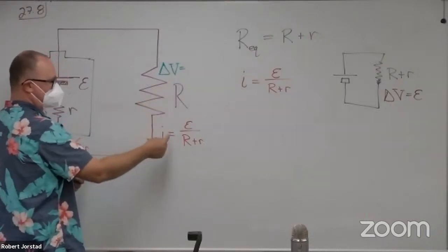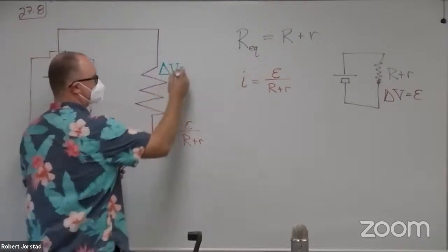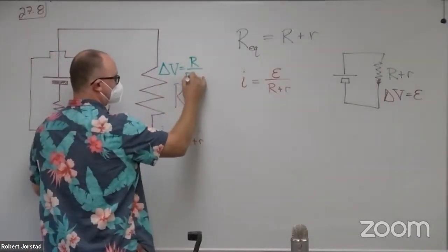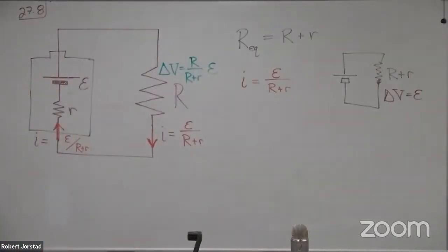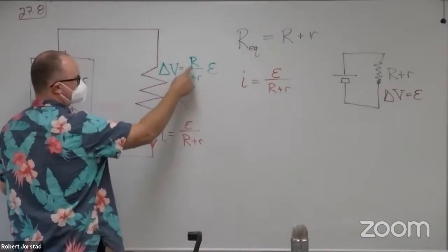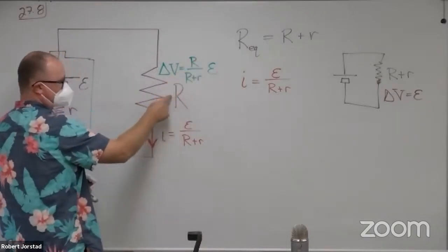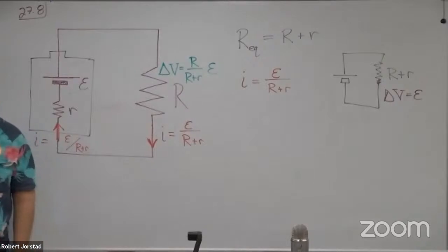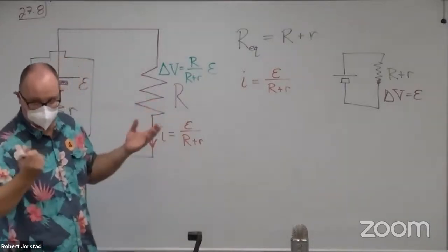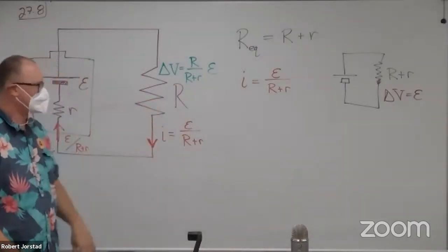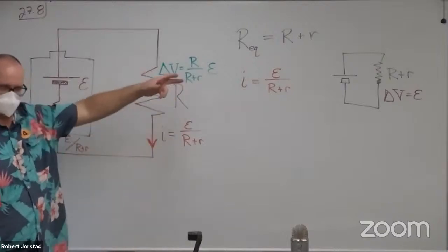So the voltage is this current times this resistance. It's close to E, but it's not quite E. It's actually the ratio of this resistor to the entire resistance. Remember I told you that before? It was the voltage divider equation I alluded to. I'm like, oh, if you saw this cool trick, you could have known this answer. Remember the 1/3 and the 2/3 volts over there?